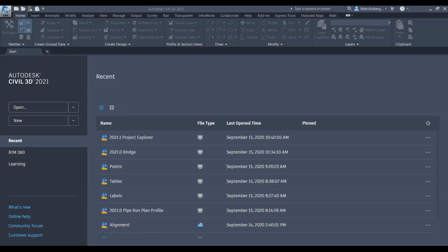All right. So a little bit of time left. And what I'll show you is sort of the highlights of what a pipe run allows us to do. So number one, it's not going to look any different right away. Only when you start making edits is it really going to sort of shine. So one edit that you would typically want to make is, well, I want to change the location of a bend, or I want to change the location of the end of my pipe, for example. So here's a pipe run. I have 100 millimeter pipes. I've got a bunch of bends. Right now they're all 90 degrees.